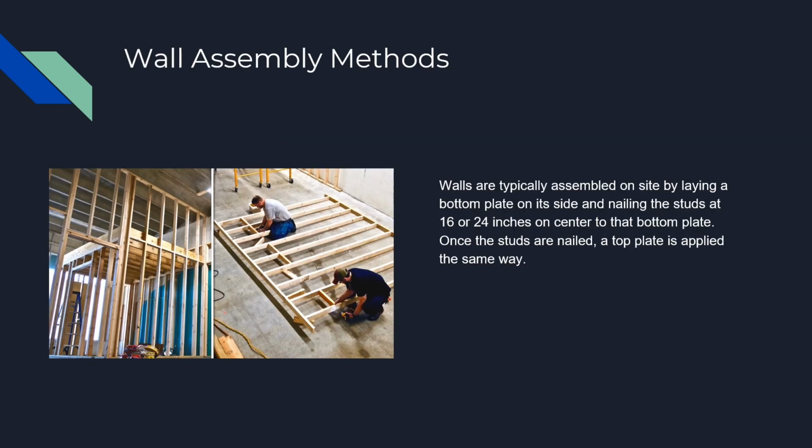Walls are typically assembled on site by laying a bottom plate on its side and nailing the studs at 16 or 24 inches on center to that bottom plate.